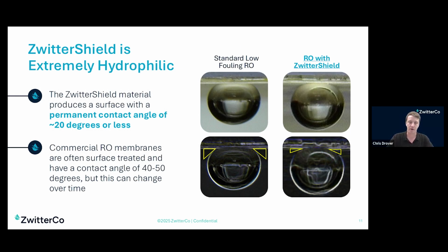We also talked earlier about the surface being really hydrophilic, and this means water loving. So one of the classic measurements you use to look at this is called contact angle. And if you're unfamiliar with it, I'll kind of explain what's going on here. What you're looking at on the screen is an inverted membrane with, at the top of a water-filled cell, a really high zoom image of a tiny air bubble up against that membrane. When we say contact angle, what we're talking about is the angle that's formed between the three-way interface between the membrane, the water, and the air.